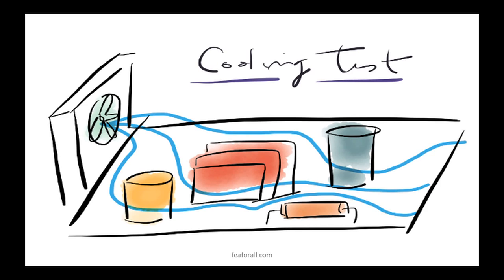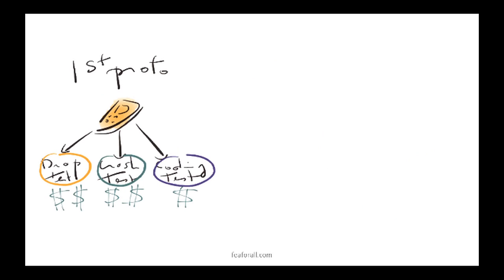Then, it is not all about strength. You also have to do thermal cooling tests, for example. Basically, it's to see if your device will not overheat during its life. This is a particularly necessary test for electronic devices because they are always on, consuming power and heating. Do you remember the last time you turned off your cell phone?